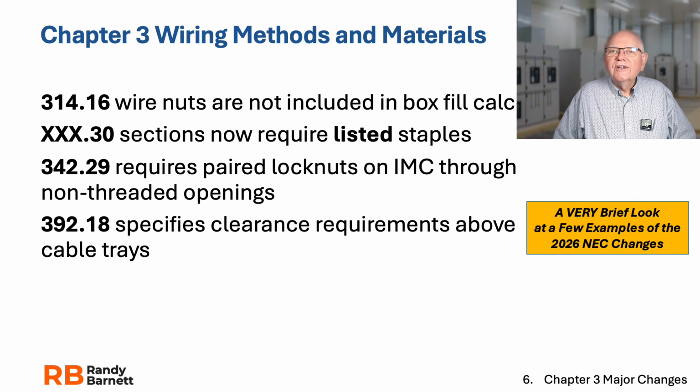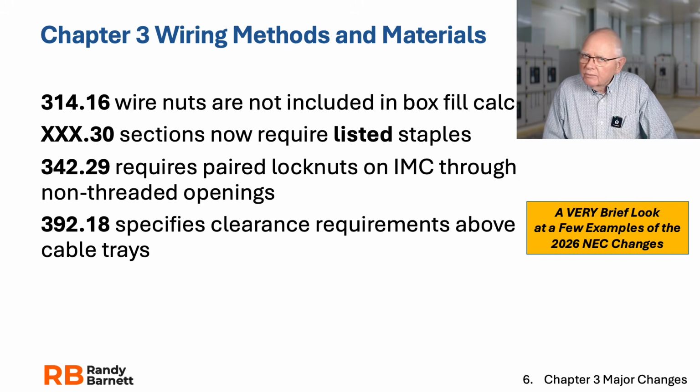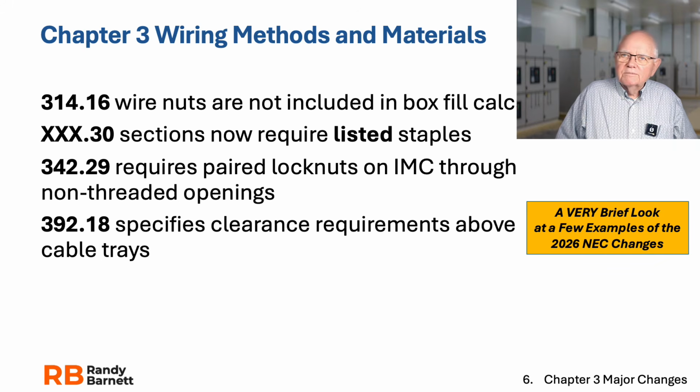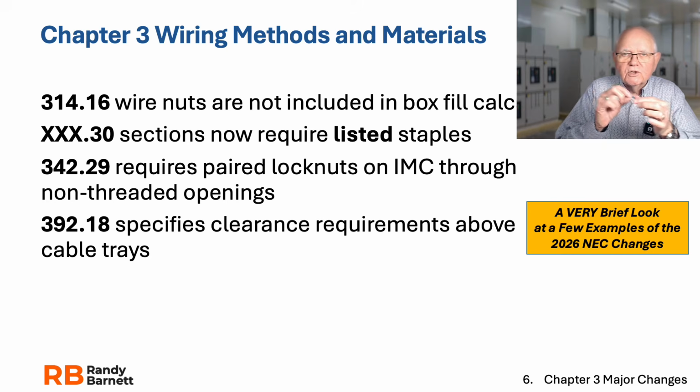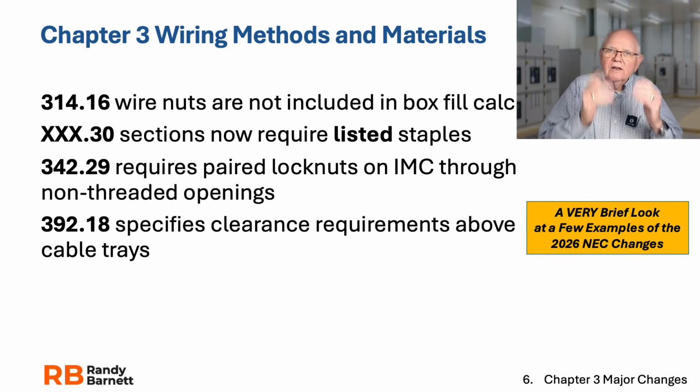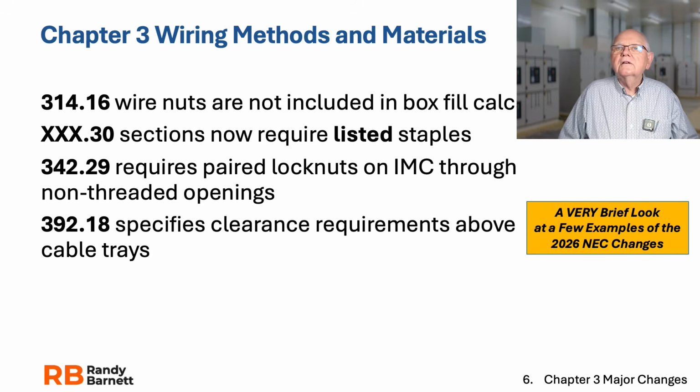314. So box fill calculations, right? Always the question, well, how about, I got some pretty big wire nuts in there. Come on, that takes up some space in that box. Yeah, you're right, it does. But do we count it in our box fill calculations? Some said yes, some said no. The answer now, 314.16, no. Wire nuts are not included in box fill calculations. And that includes if you're using a little push-in square, or when you push the clamp down and lock it in place, whatever. Those are not used in box fill calculations.